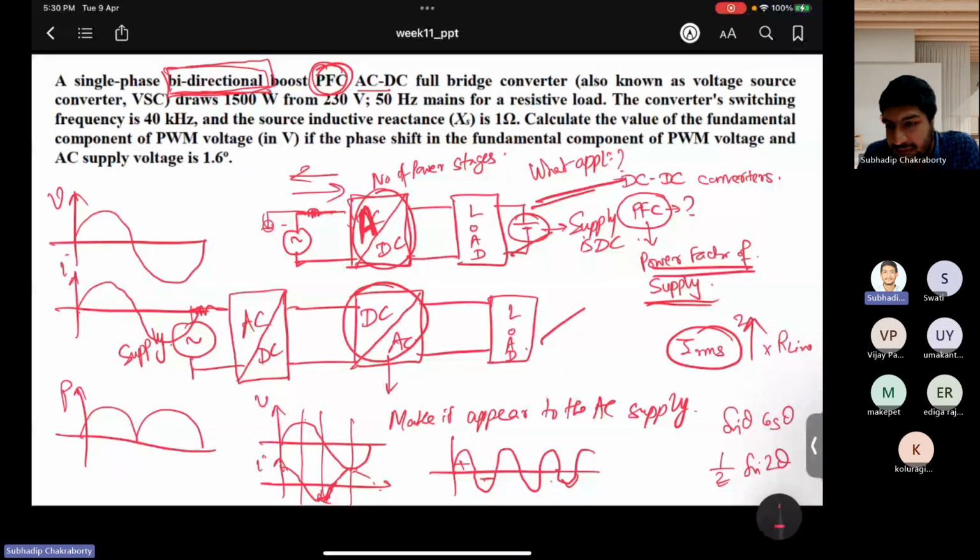your aim is to slow down the vehicle, so not to dissipate the stored kinetic energy in the wheels in the environment using mechanical brake pads. Otherwise, you can use the energy stored in the wheels to charge the battery. That's why he meant bidirectional power transfer. So that is one application.